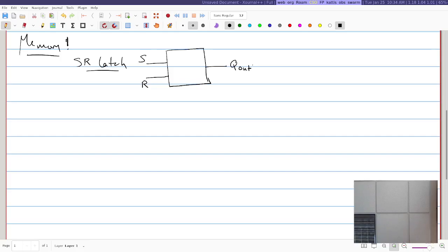When we have a circuit, we literally have the output loop back as an input. We're going to call this Q in. Q in is whatever value the output was last time. I'm waving my hands a little bit, and we'll get more into that in a second. But basically, Q in is what the output currently is, and then the circuit uses that to figure out what it wants to do next. And you'll see this is the trick. This is the one trick that lets us build memory out of logic gates: we can have circuits that loop back, so their outputs go back as inputs.